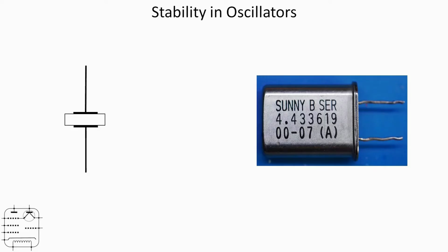It's something I recovered from a circuit board, 4.433619 megahertz apparently. So you can see these things can be manufactured to a very precise frequency, and that in itself is probably the subject of half a dozen videos. And there's crystals everywhere. They're in your phone, they're in digital watches, they're in computers. They really are everywhere. Now there are a number of materials that you can actually make a crystal from, although pretty much all of them are made from quartz.